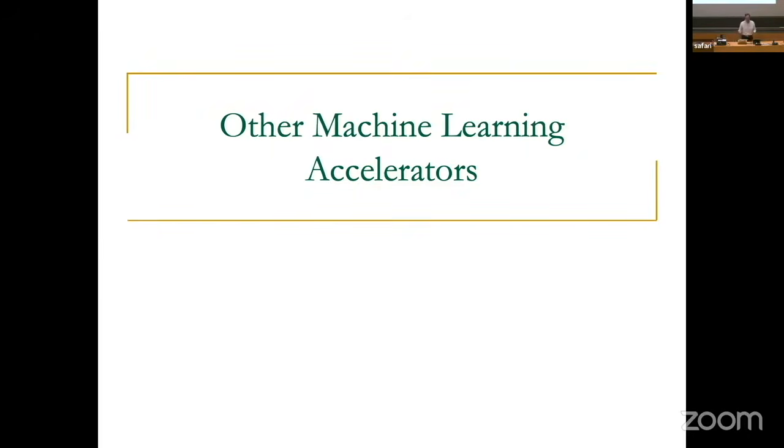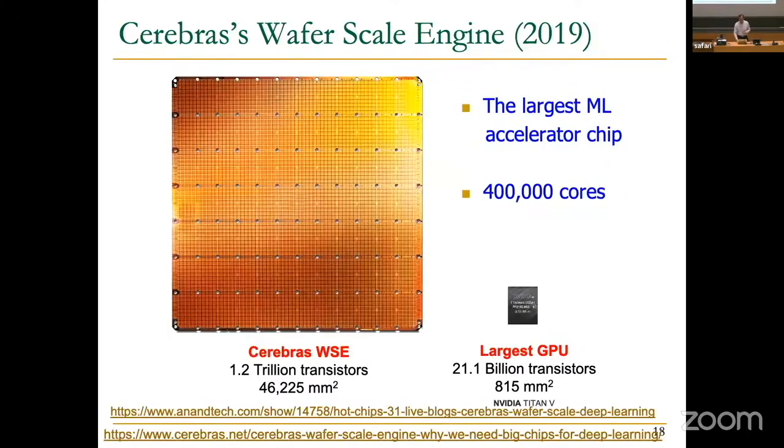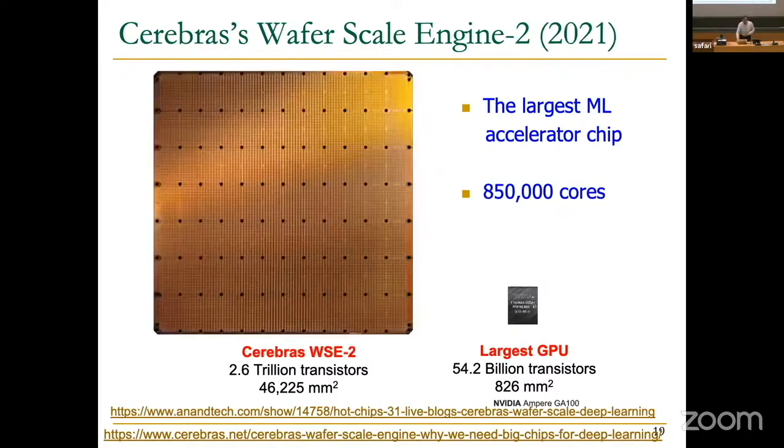So basically, people have been using SIMD architectures, and this is later today. I will show you that at the core of it, this has many processors inside. Well, this is the newer version, if you will. This has many processors inside, and each processor is a SIMD processor internally, and they communicate with each other. So it actually consists of multiple paradigms. It's a multiprocessor of SIMD processors or vector processors, if you will.